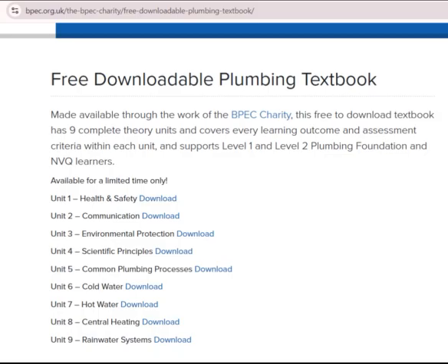Ceramics and fireclays. Ceramics and fireclays are used extensively in the plumbing industry for sanitary appliances, heavy-duty sinks, underground pipes and wall tiles. There are three basic types. A. Vitreous china. This is a clay material, which is sprayed with an enameled surface. It is used to manufacture bathroom appliances such as WCs and cisterns, wash hand basins and bidets.